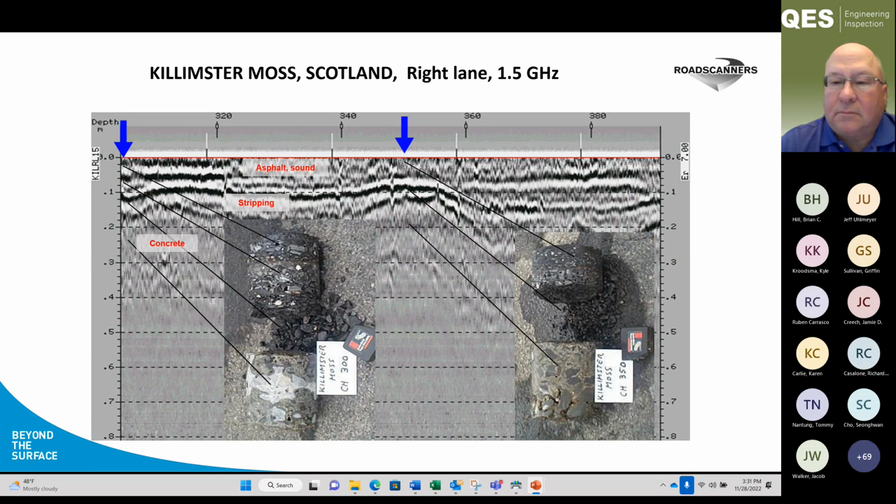Then the next case about stripping is from Scotland. A few years beyond, I think this is from 2005, and now we have a concrete road, actually very unorthodox concrete road building over a moss or peat bog in the 20s, and then overlaid with the asphalt, and once it was exposed to the heavy traffic, it very quickly started to have major stripping problems.